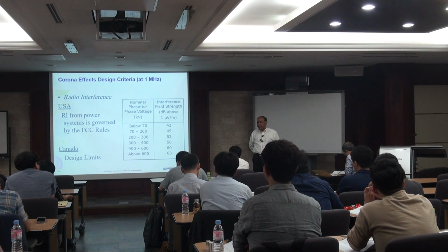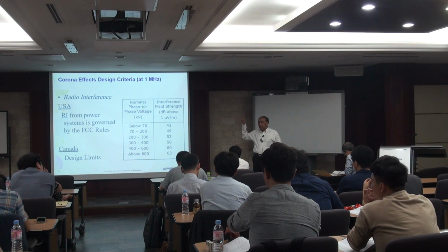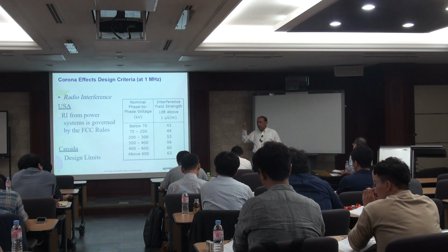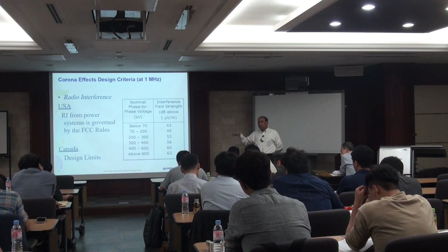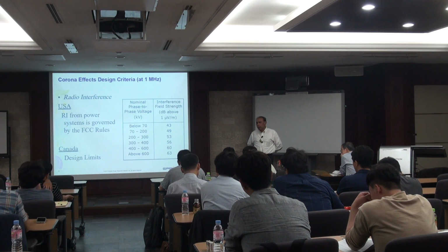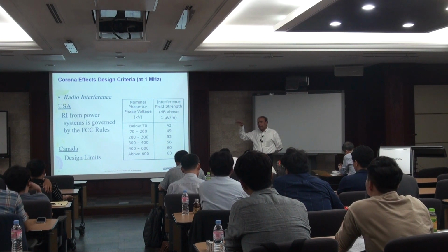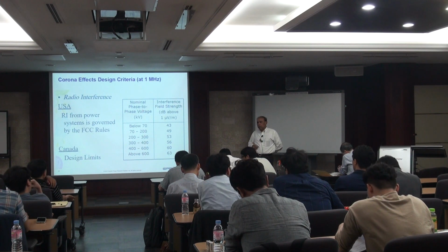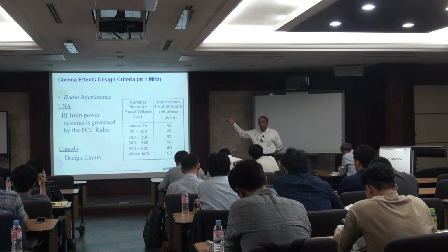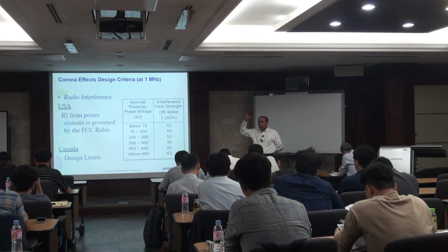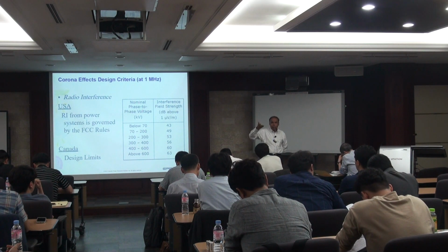So actually the idea in the future is to measure underneath the energized HVDC lines and see are they still within the limits, or what else we have to do to reduce or increase them. All that is the research topic. We started some projects measuring electric fields underneath the energized lines. John is going to cover ESCOM South Africa lines, Manitoba Hydro lines, and BPA lines. We are putting instrumentation under actual real lines and will come up with some numbers in the future.